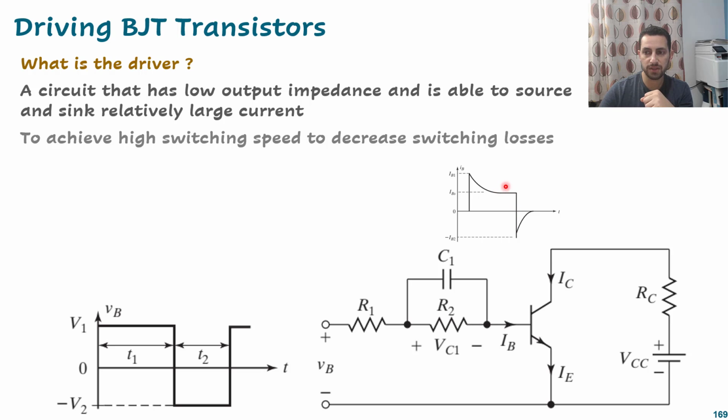So during this time, it goes through R1 and R2, but during that time, it goes through R1 and C1. This is one of the tricks they use to push instantaneous current into any other circuits or other terminals. And when we supply the negative voltage, it peaks also, but in negative, okay? And we use this negative one to make the switch off very quickly.